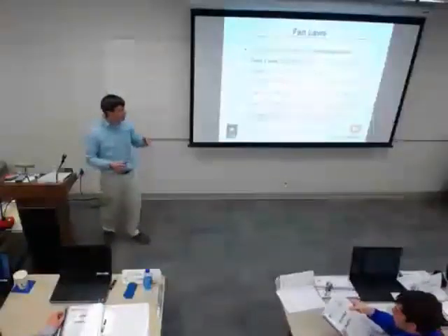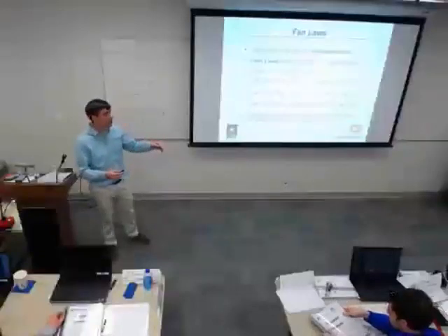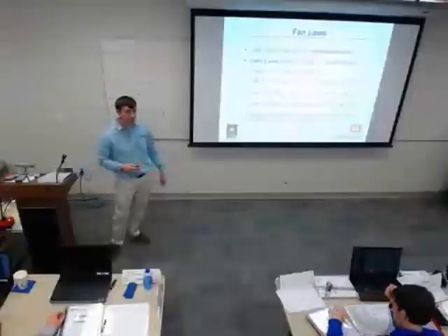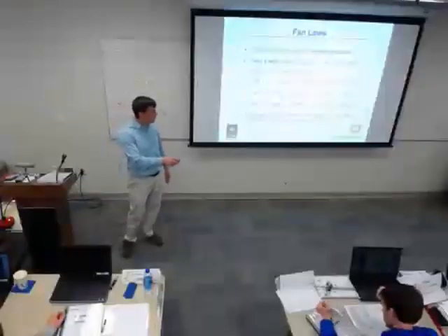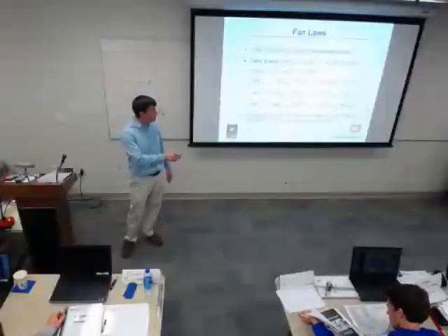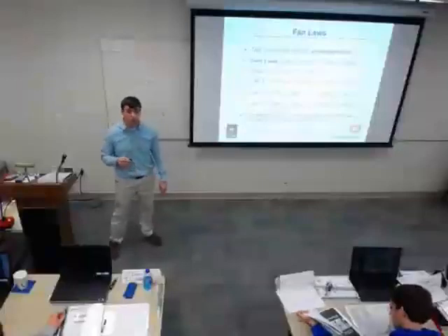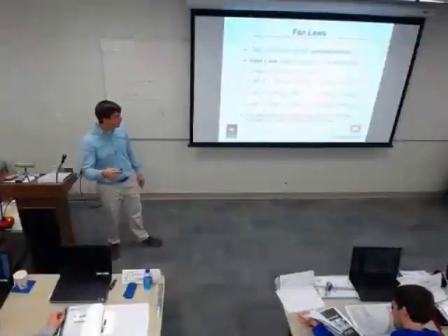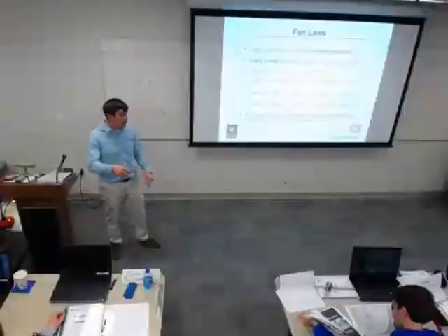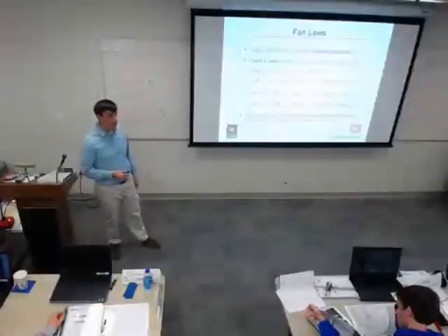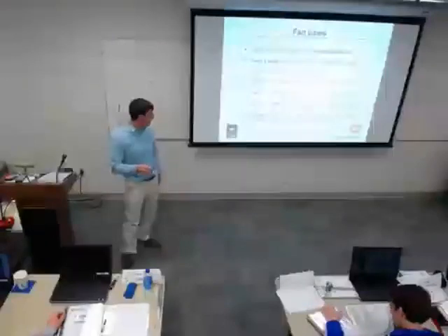If I make a change in fan RPM, I will see a corresponding linear change in CFM. With pressure, if I make a change in RPM, my change in pressure is going to follow the squared relationship of that. And the kicker is horsepower, which you can equate to current, is cubic. We'll show you how those numbers work out in just a minute.